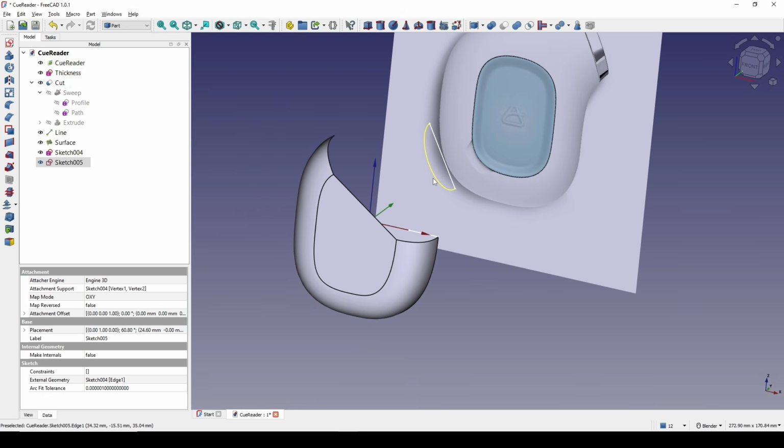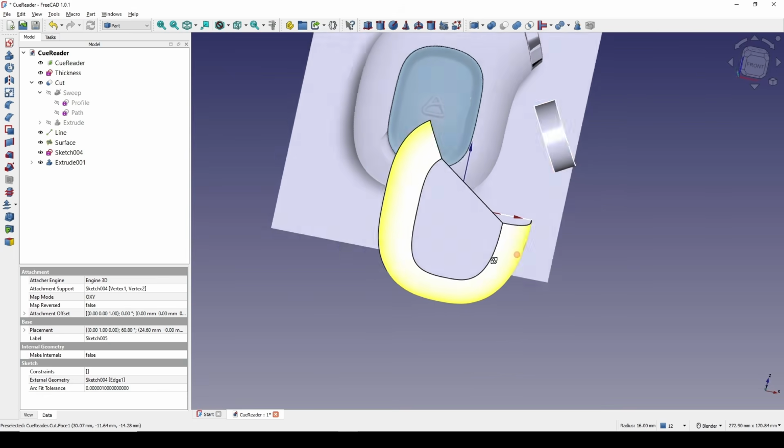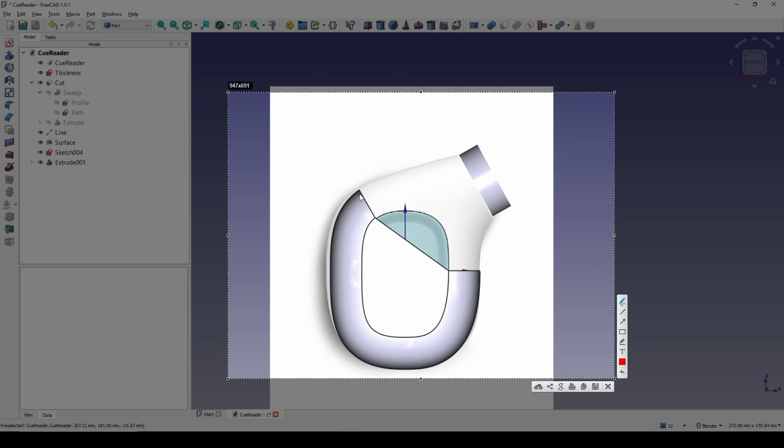Now I will extrude this one to the normal direction. I click on this one, go to extrude, and let's extrude this one to 10 and OK. Okay, this is what I want. The next step is I want to create plane curves connecting this edge and this edge, this edge and this edge. And also I want to split this one to have a line in the middle here. And I also create a plane curve in between. And from there, I will fill the surface number 1 up here and number 2 down here.